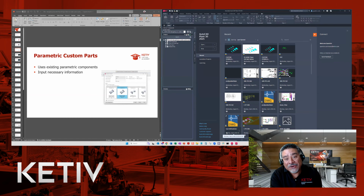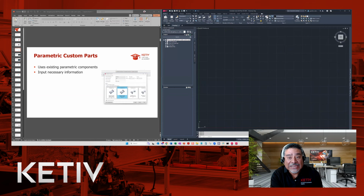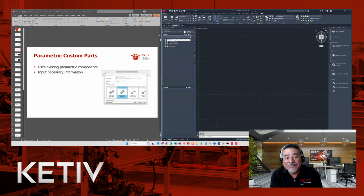Once you get that all figured, then you're going to create a project over here in Plant, and that's where you're going to pull your spec from. So your spec is going to contain all these different components that you put in from the catalog in here. And basically, when you do that, you'll get these available to use. Let me show you this right here. These will come in here, and then you can pull from these and add them to build your models with in Plant 3D.